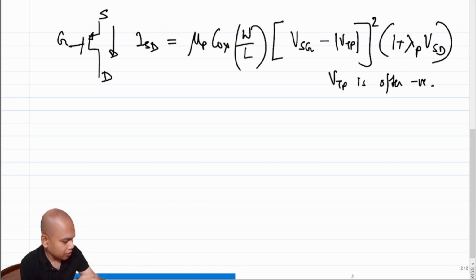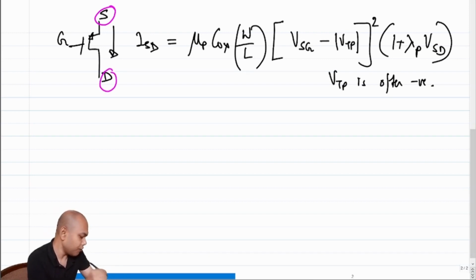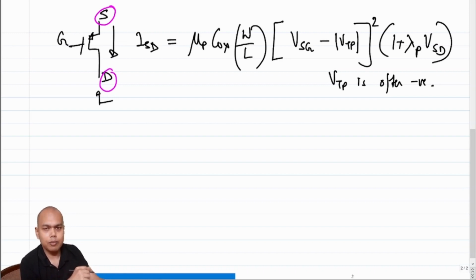So that was the whole reason for investing time in this. And what is a good thing about this p-MOS transistor? The higher potential is source, lower potential is drain, and if it is biased in saturation, the incremental impedance looking into the drain will be RDSP, which can potentially be as high as the RDS of an n-MOS transistor.